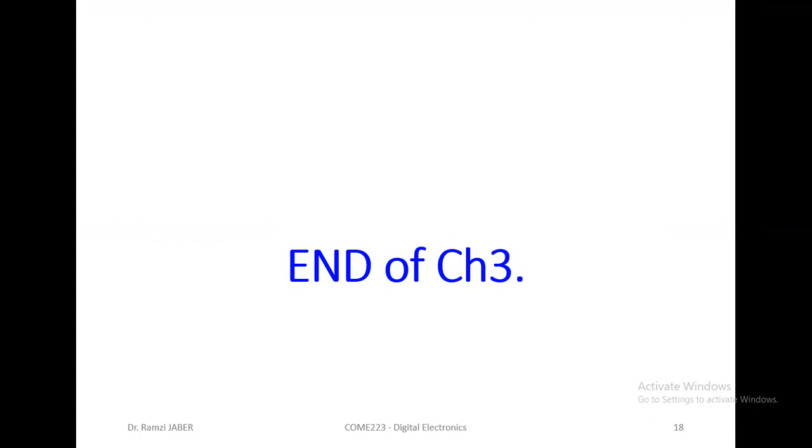We want to use it in digital electronics. So RTL BJT transistors are not recommended to be used in digital electronics, because the output is not optimal. Always we lose in VCE. Always we have 0.2 volt lost. Okay, this is the summary of chapter 3.